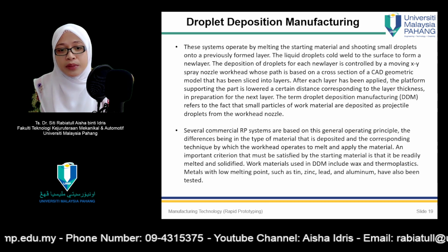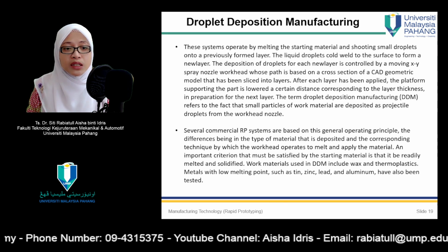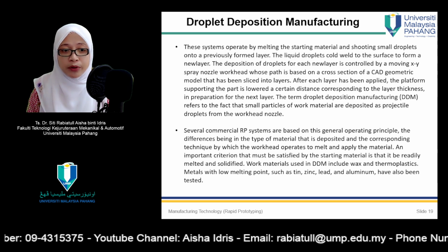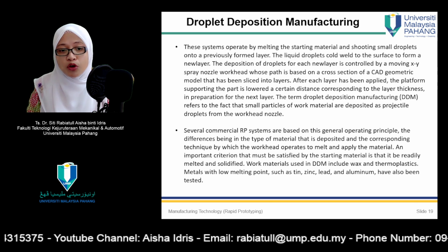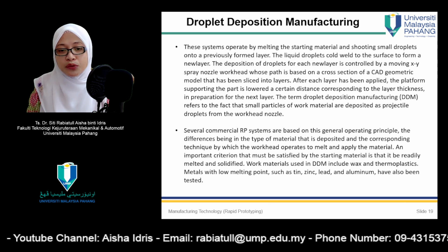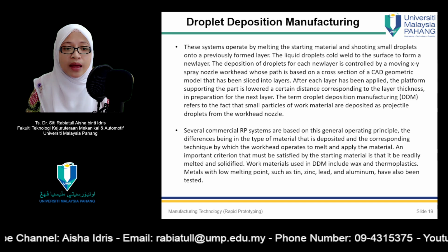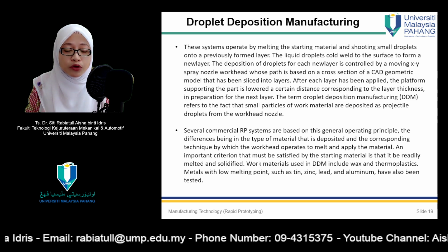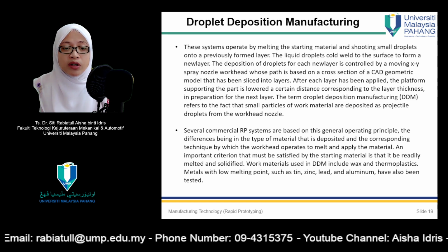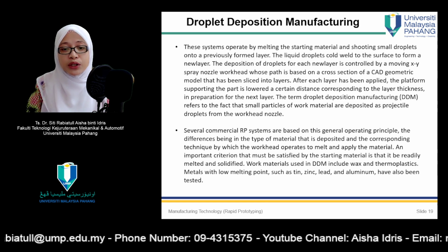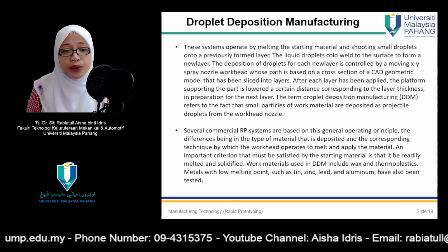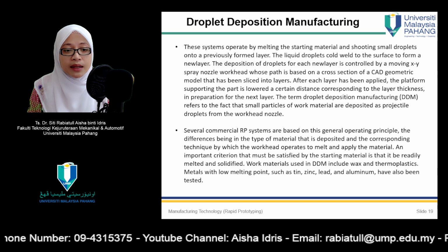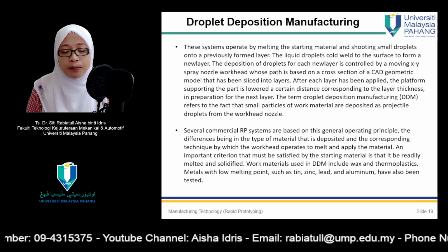After each layer has been applied, the platform supporting the part is lowered a certain distance corresponding to the layer thickness in preparation for the next layer. The term droplet deposition manufacturing, DDM, refers to the fact that small particles of work material are deposited as projectile droplets from the workhead nozzle. Several commercial RP systems are based on this general operating principle, the differences being in the types of material that is deposited and the corresponding technique by which the workhead operates to melt and apply the material.